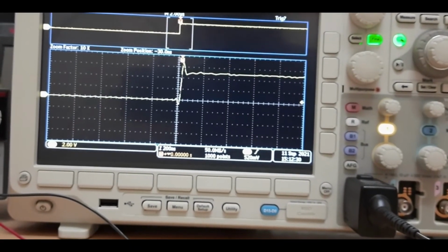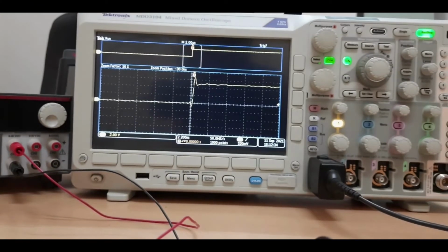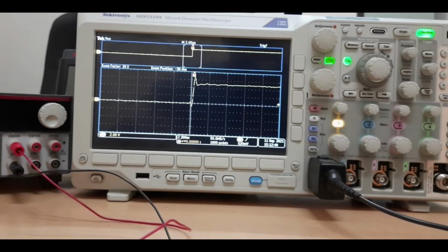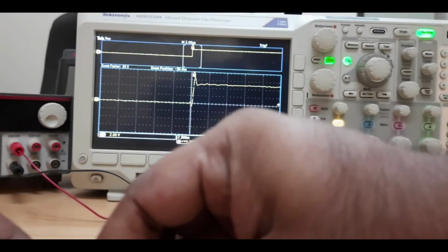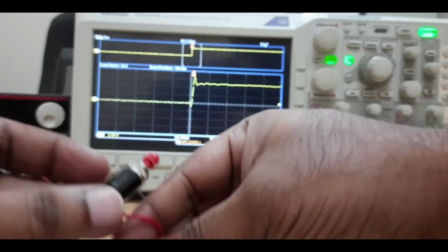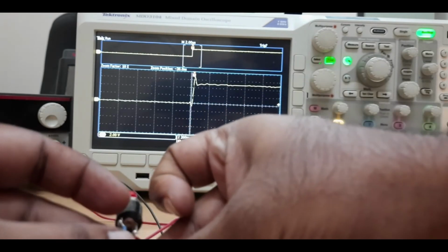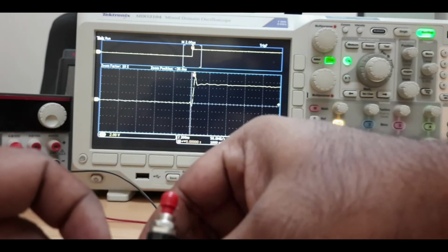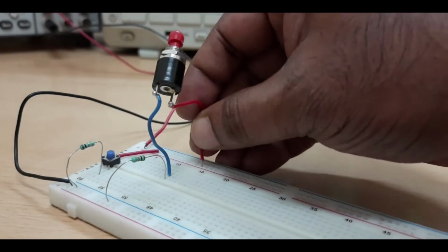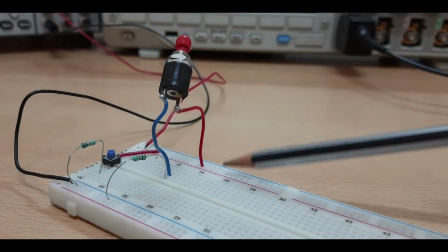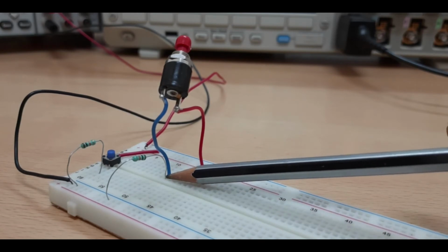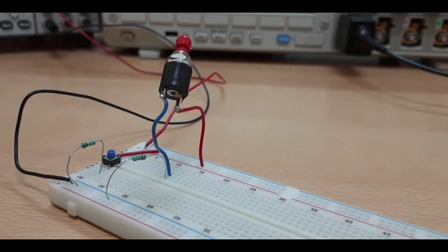Let me change the switch and show you that this behavior may change from switch to switch. For that, I am going to connect another switch again using the pull down technique. So I am connecting the second switch to my breadboard, and you can see now I have connected my second switch. Here this switch is connected to VCC, and then the second terminal of the switch is connected to a resistance which is going to ground. This resistance is of 10 kilo ohm.